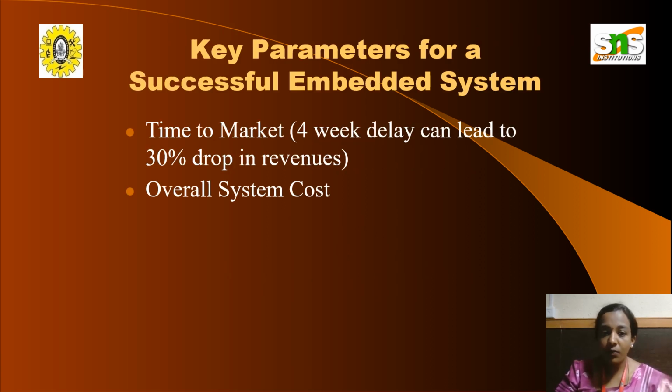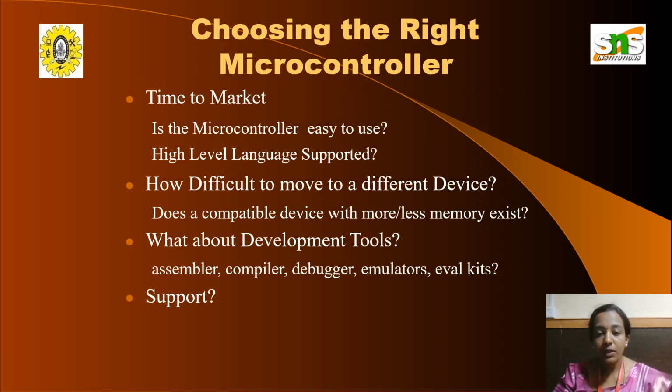The key parameters for a successful embedded system are time to market and overall system cost. Choosing the right microcontroller is very important for time to market. Does it support a high level language? Is it easy to use, is it a compatible device, can we make use of the complete memory? Is the memory capacity of the RAM or the ROM sufficient?